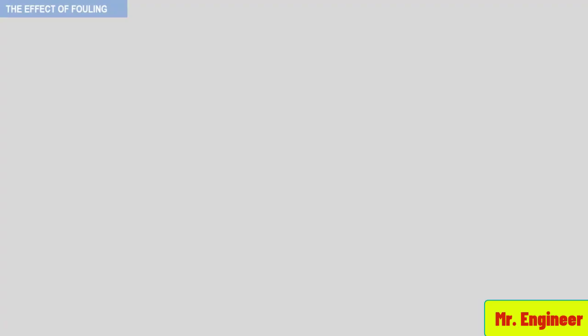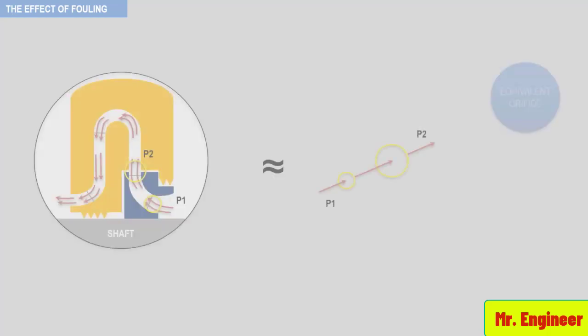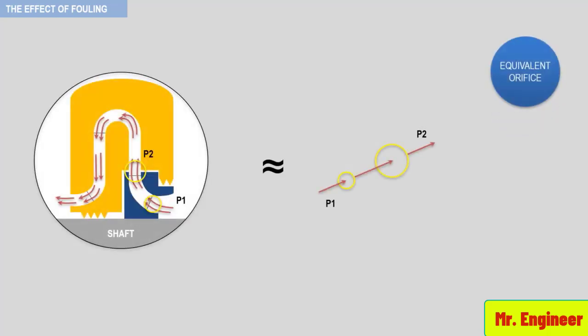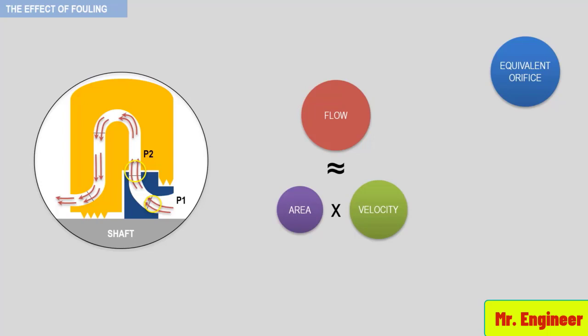As already discussed in a previous video, you can reduce any blade row or impeller to a series of equivalent orifices, as depicted in this example. Recall that flow is a function of area and velocity. Whenever any blade row or impeller is designed, the designer sets inlet and discharge blade areas such that optimum velocities relative to the blade will be achieved at each location.